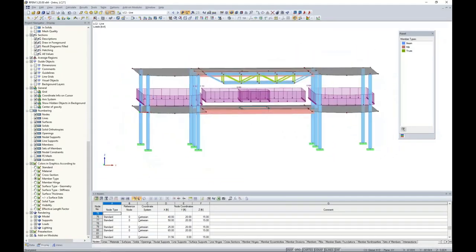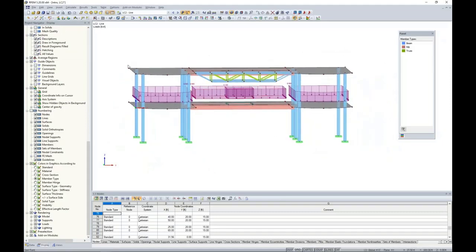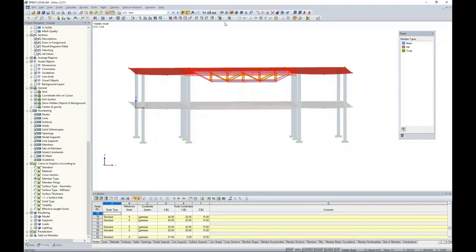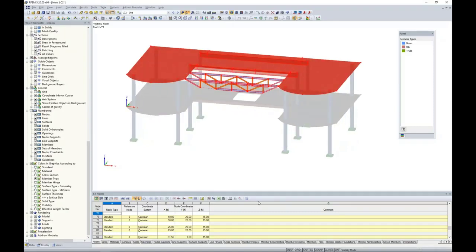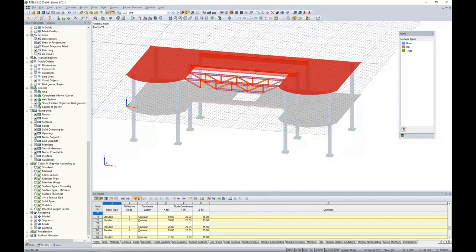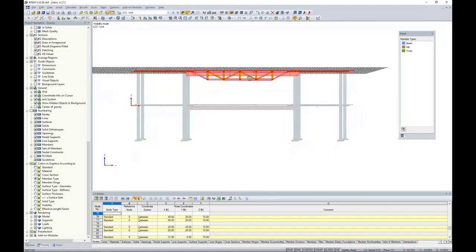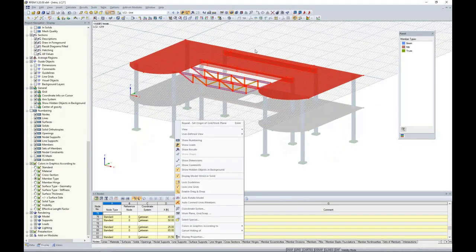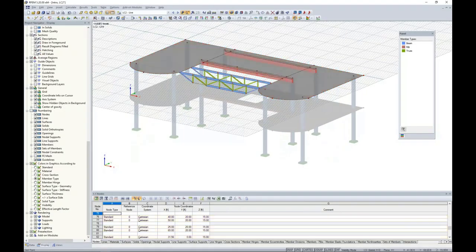Well, the first thing I'm going to do is create a user-defined visibility of only my second level. I choose that with my selection box, and then I choose visibility by selected objects. I turn back on my grid, and I'm going to utilize this option here to set the origin of the grid work plane to the upper left corner. So now you can see that the drawing grid is just located at my second level instead.